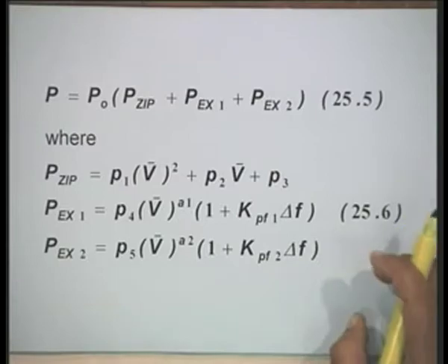In fact, the load models which have been used in analyzing the stability of the system, the results which are obtained, and the actual thing which happens on the ground, may differ. Suppose for a given operating condition my stability study shows that I have this much stability margin, while in practice you will not achieve that much.